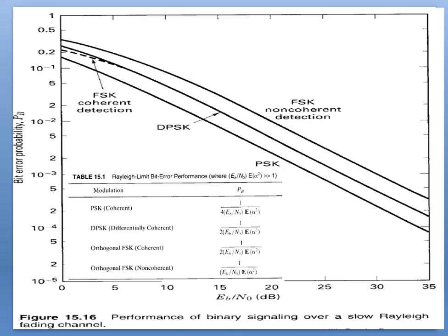The plots of bit error versus Eb/N0 for the signaling schemes show the exponential relations. However, under multipath conditions, if there is no specular signaling component, alpha is a Rayleigh distributed random variable, or equivalently, alpha squared is described by a chi-square PDF under Rayleigh fading conditions.